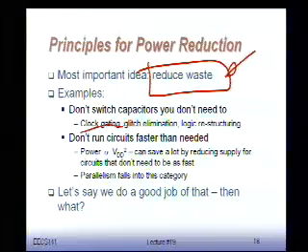So clock gating, turning off clocks when you don't need them, eliminating glitches, logic restructuring to basically eliminate glitches or make your logic simpler. All those things are very useful. The other thing is, as I already mentioned, don't be macho.